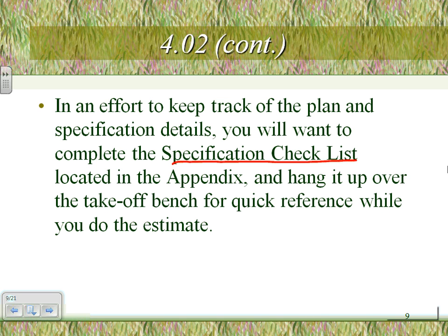Labor unit adjustment. Do I need to adjust the labor unit for any one or all of the following? So check. For example, do I have ladders and scaffolds? Yep, check. Then you have to make sure that you adjust for that one. Rob, my friend, this will decide if you're going to be using, remember that NECA 1, 2, 3? Based on this sheet, you have to decide if this will be a normal, standard work condition, difficult, or very difficult, based on these checks.